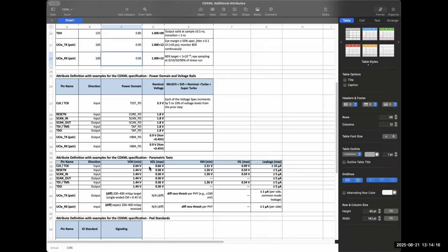And all the cells are characterized for this level spec, and there is an appropriate frequency target for each of those voltage domains across the internal PLLs and the respective sub-clock domains, right? So all those informations are also available in the PD database.